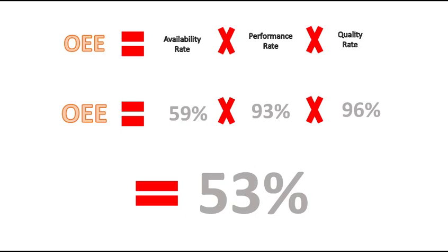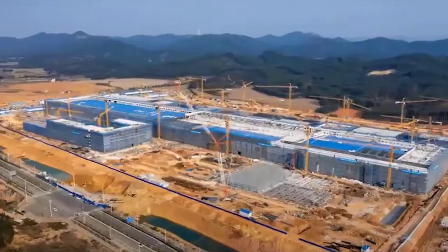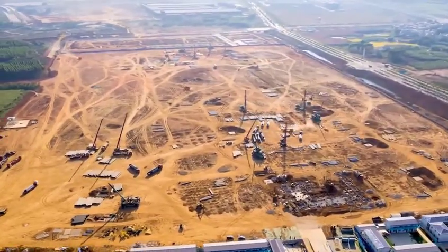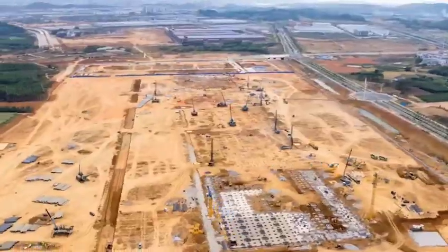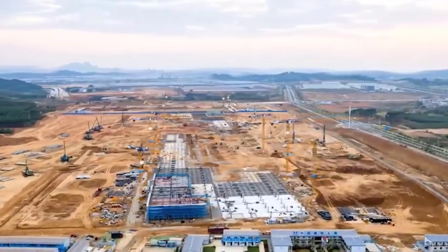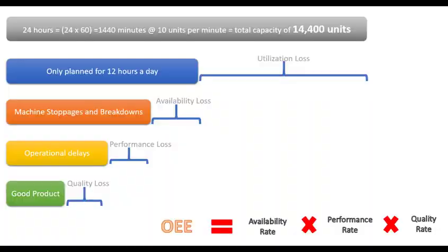world-class manufacturing. To maximize production output per line or per shift or per factory, before making decisions to invest in a capital program, you need to look at OEE percentage together with the fourth lever, utilization, and make sure that all these 4 levers are maximized before embarking on capex expansion. Remember, utilization was 33% as a result of only operating 8 of the 24 hours. So if you are struggling to meet volume demand, you can simply increase utilization by working extended shifts of 12 hours. Then utilization increases to just less than 50%, taking into account lunch stops.